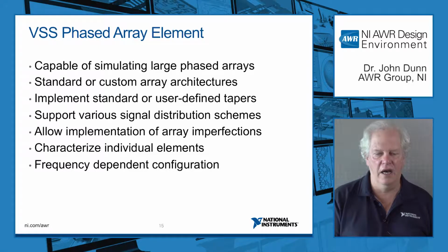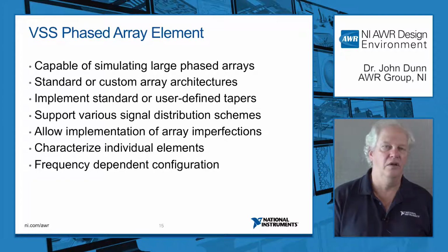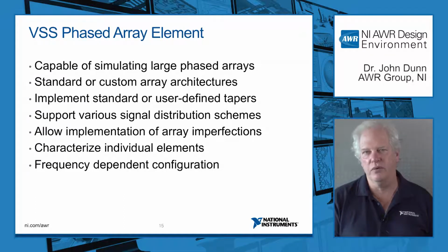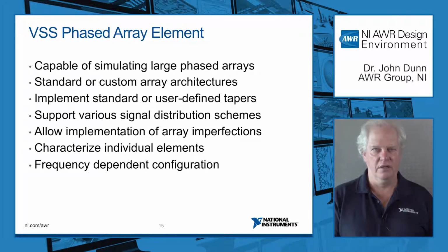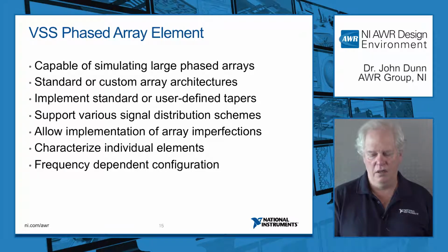Let's move on to the element I was talking about in the system simulator in VSS and take a quick look at that. Again, we're thinking phased arrays here, and what this model does is essentially you set up the array equation, say how many elements you have in the array, the geometry of the array, and then it will use those equations to calculate the propagation, the coupling, etc. You could have a transmitter or a receiver, for example, and you can throw that into your system simulation.